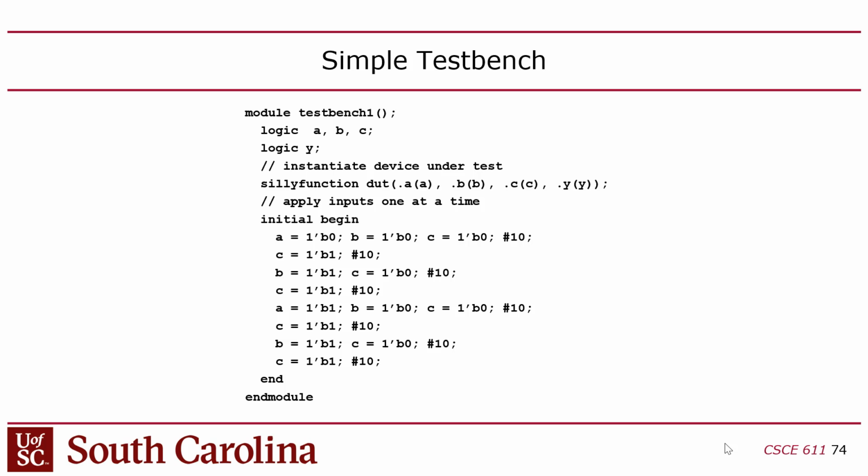You see this hash 10, hash sign 10, pound sign 10? Whatever that thing's called, right? This will delay the simulation for 10 units. Why? Because remember I mentioned there's no delay when you simulate behavior, right? Because there's no underlying device technology that's being considered here. We're just testing the logic behavior. We don't have any kind of logic delay idea of how long it takes to propagate logic, how long it takes to charge and discharge the capacitors that create the logic. We're not simulating that. We're just simulating the behavior.